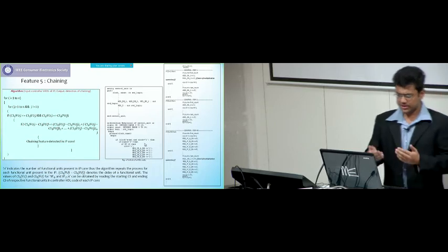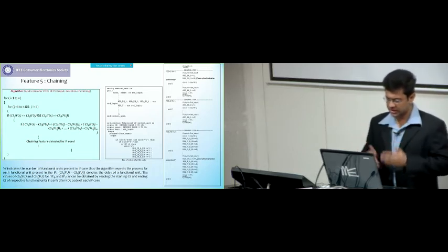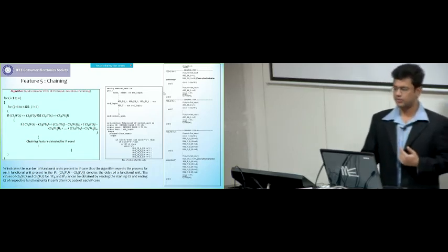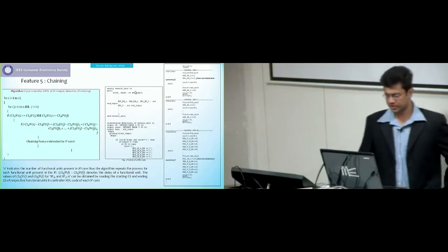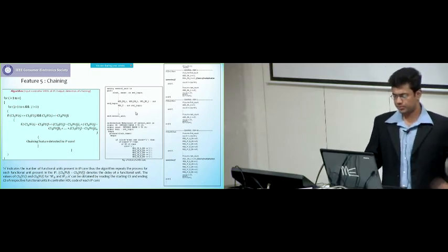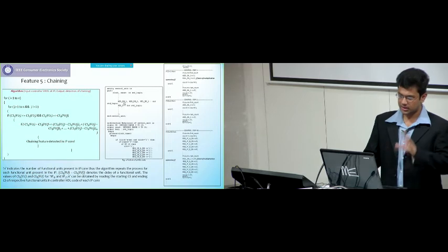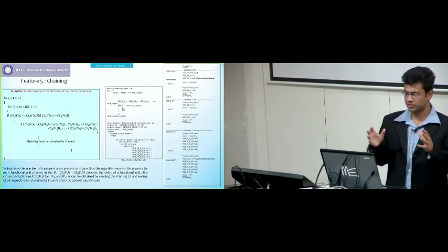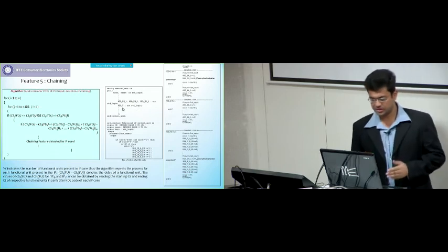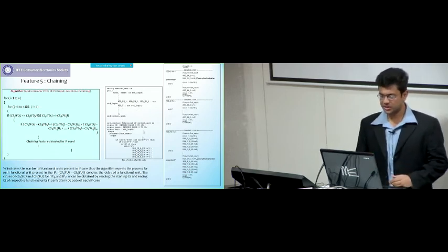I can give you some more examples. So typically in an HDL file, I have taken a snap of our project and put it over here. We have the portion of the controller, and we have the entity portion which declares the primary inputs and outputs in terms of the ports, and we have the architecture where different types of signals are declared.